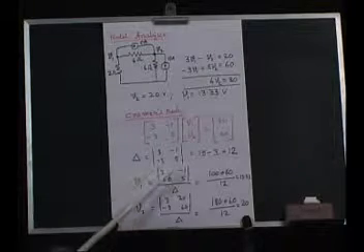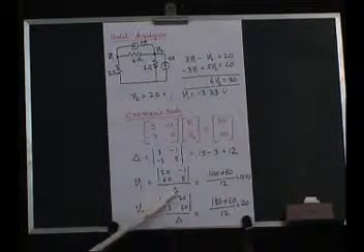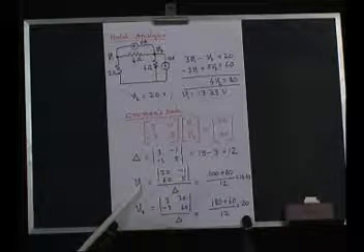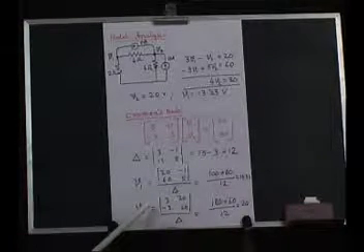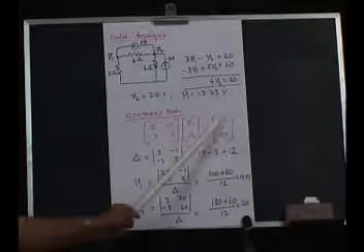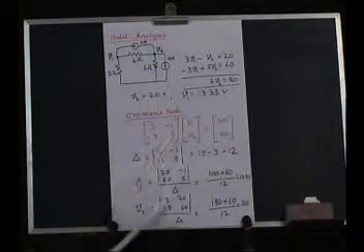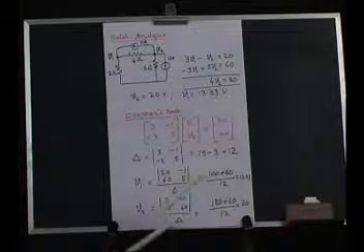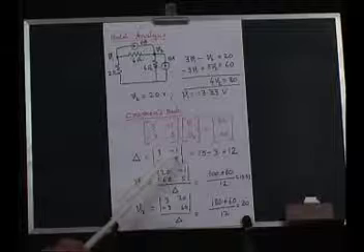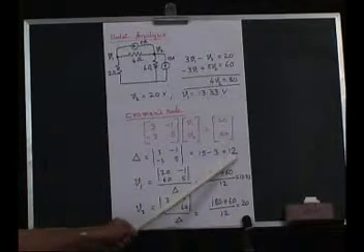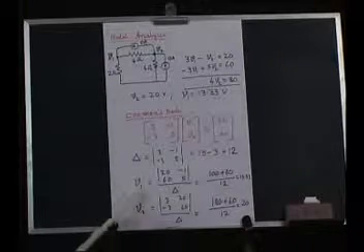So, we get delta 1. Delta is the determinant of this particular matrix, which is equal to 12. So, we can find V1, and to find V2 we remove this and put 20 and 60 here and find the determinant value. We get the determinant value here, and the coefficient determinant we will get as 12. We have previously found this. So, we can find V1 and V2.